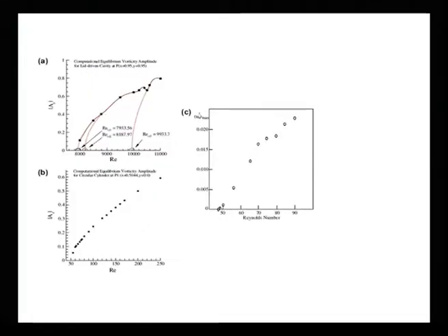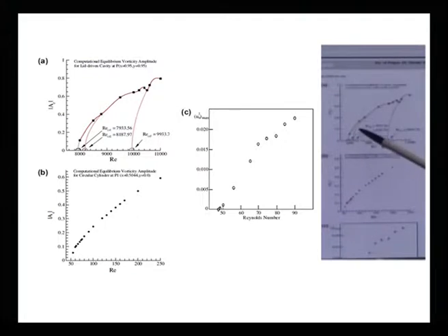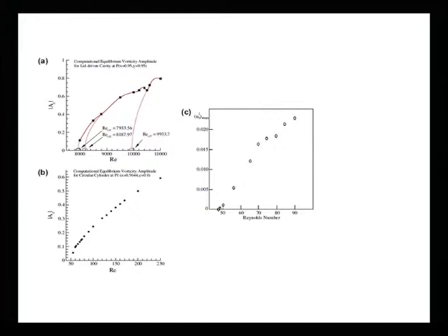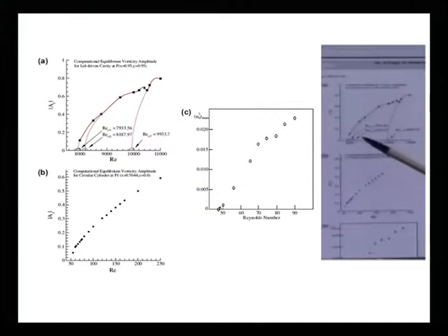If we now obtain the equilibrium amplitude and plot it as a function of Reynolds number, then what we are going to get is the equilibrium amplitude versus Re for this lid driven cavity problem. And exactly like what we saw there, it is not a purely parabolic profile as the Landau equation would have demanded, but instead you are going to get this equilibrium amplitude to fall on various polynomials, and in concert with what we have talked about earlier, we talk about multiple Hopf bifurcations, and different Reynolds numbers are noted here.